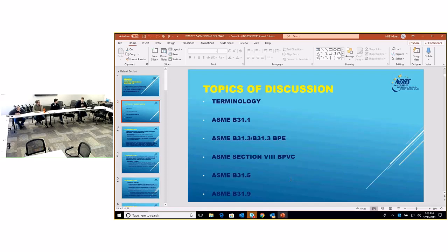So initially I went at the owner with, this was not in the documents, but we need PSVs on all of our storage tanks, which need to be Section 8, in addition to our boiler, our expansion tanks, buffer tank, and the piping system needs protected for this condition, and a PSV on the B side of that heat exchanger. So I had a bunch of back and forth with the owner, and the owner said, nope, you're B31.9, you're fine. And I said, well, send that to me in writing.